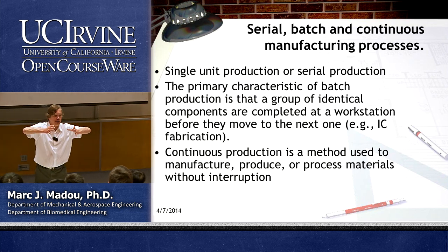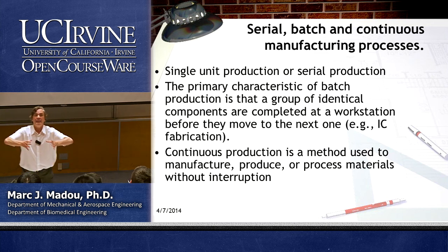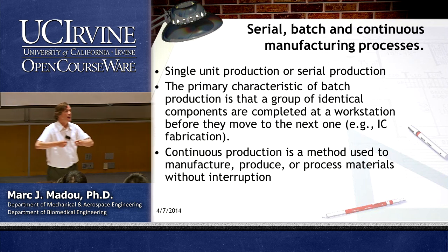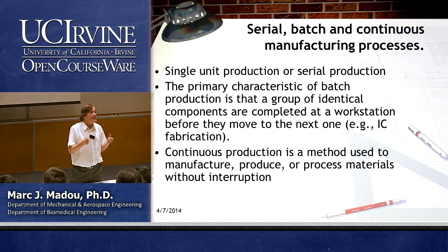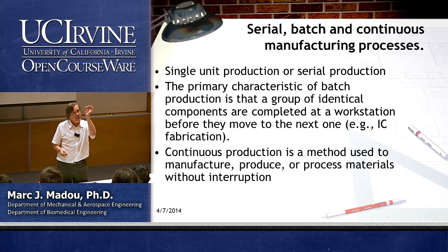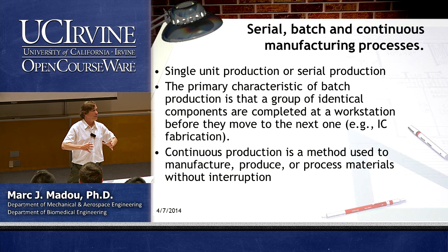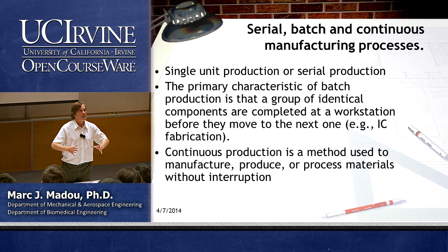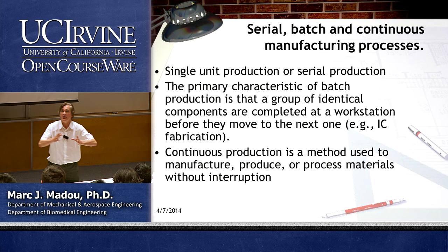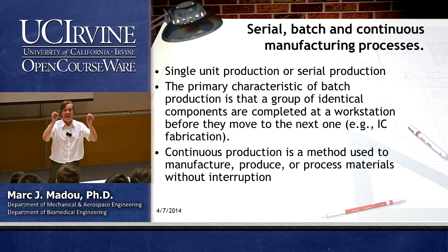In batch, you have on one substrate perhaps 600 devices that are all made at the same time. They're all identical. That is what has caused this dramatic revolution in the electronics world. The fact that instead of making one transistor at a time, I built thousands of circuitries, transistors, all at the same time. That wafer, with all of these processed ICs, only went from station to station when the previous step was done over all of the devices, batch.